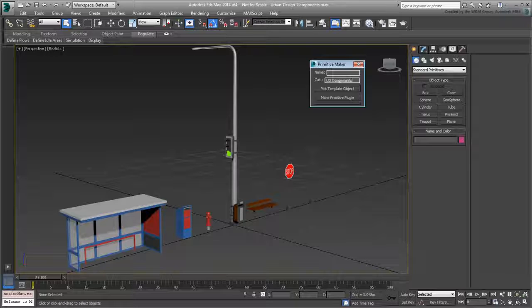You need to set a name for the primitive. This will be used as a button label, but also as a base object name. In your case, it's important that all primitives added to the city block scene start with the prefix UDC_. As mentioned before, this is part of the scene management approach we have adopted to make objects easier to select. Set the name as UDC_stop. It's not very elegant, but it'll serve its purpose well enough.